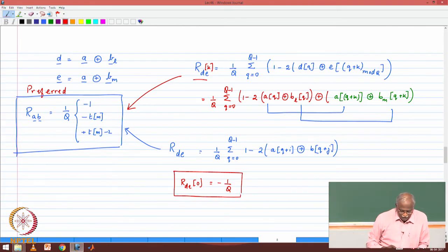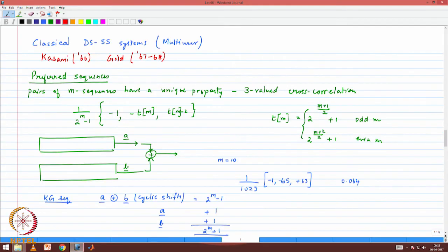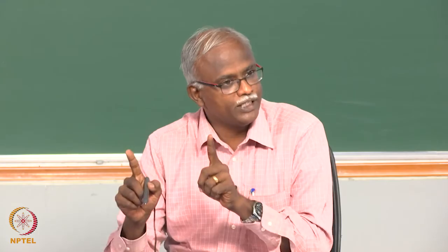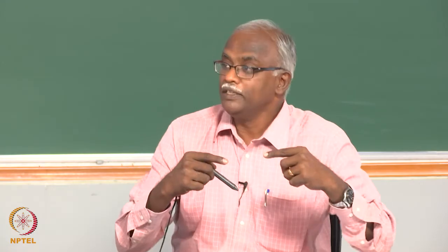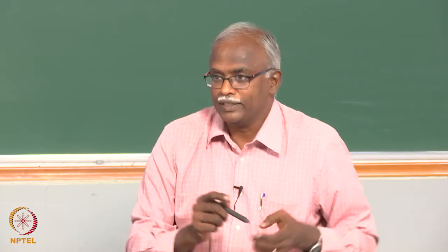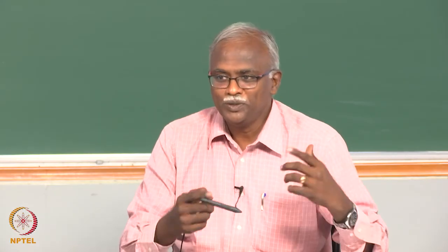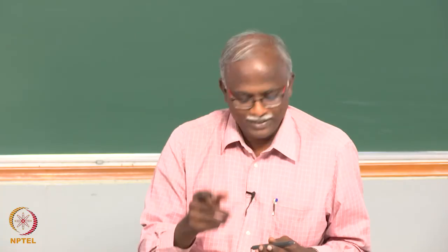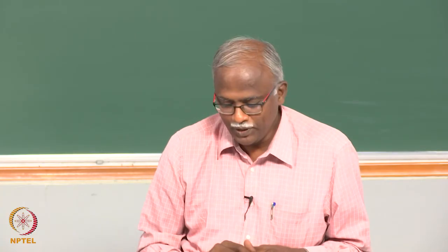Okay. Now let us ask the following question. Is the Kasami-Gold sequence set something that would have been obvious to you, having studied what you have already studied? Let's go back and look at this. What did we say was the drawback of using M sequences for a multi-user environment? The different shifts are the different M sequences, and we cannot differentiate between multi-user and multipath. Now, what did we do in cdma2000 to differentiate between multi-user and multipath? Scrambled it. What are the Kasami doing? Scrambling.